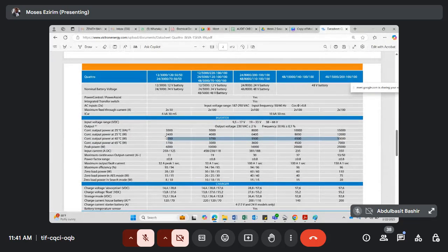So that means if I realize that where I want to install, I won't put an AC there, the temperature should be within the range of 35 to 40. Then I will size based on that, that means instead of using 3 kVA, the capacity will be 2.4 kilowatts. When I realize that the temperature there is going to be very hot, maybe 65 degrees Celsius, then this is what I'm going to size it with. Do you understand that?